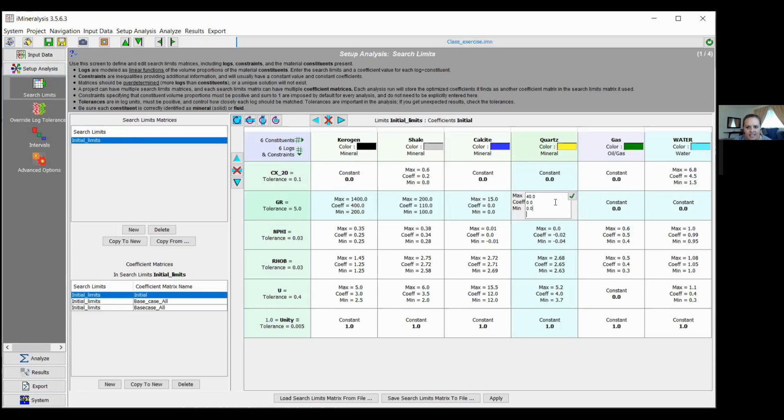And we can say, well, let's change the quartz. You still don't expect to have too much there. I'm going to put a little bit of gamma ray here, and a little bit of calcite. That I'm not even going to try to change. If I run that, it's not going to change the kerogen too much. So what I'm going to do is increase my kerogen gamma ray to a large number, to 800. And I'm going to click here, and you have to click apply. A best practice to do this is that I usually make a copy. It's just that to save some time, just do it in the same initial one, so it's going to be easier to compare.